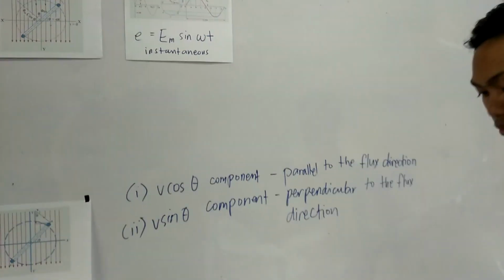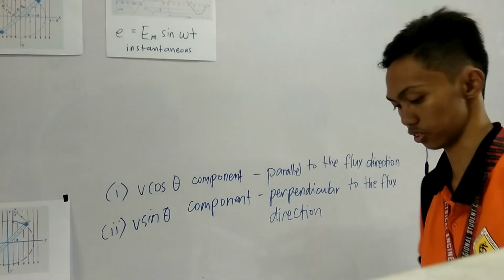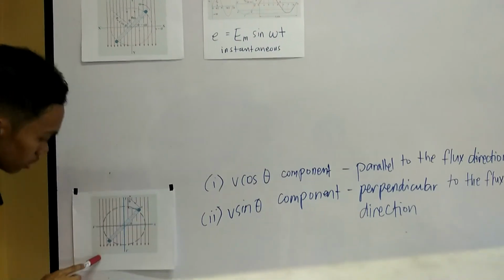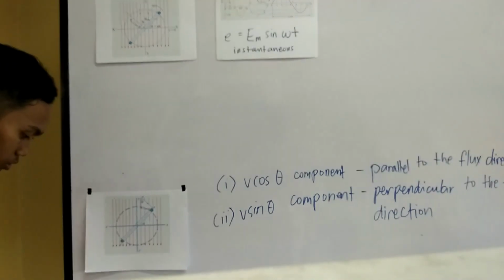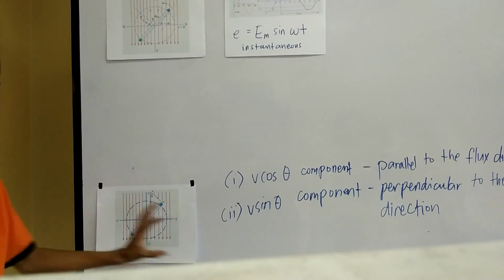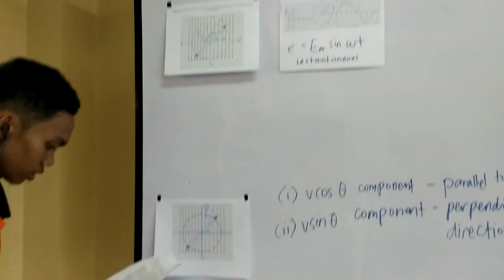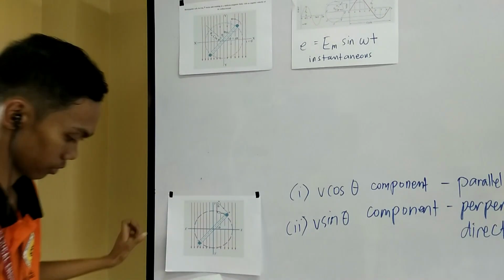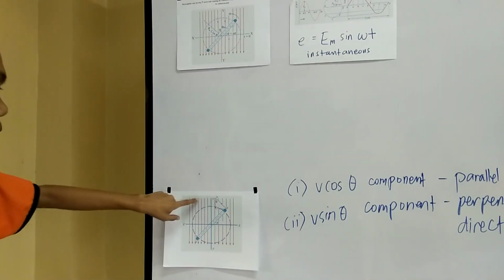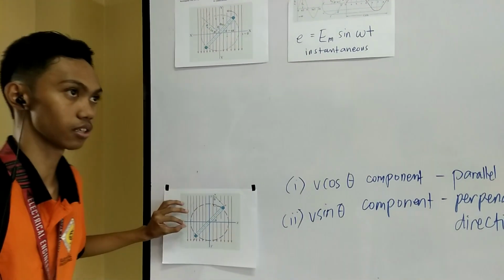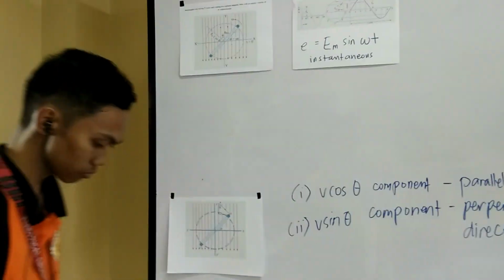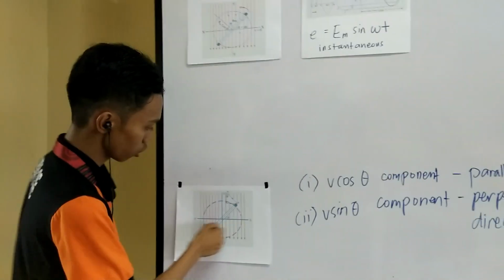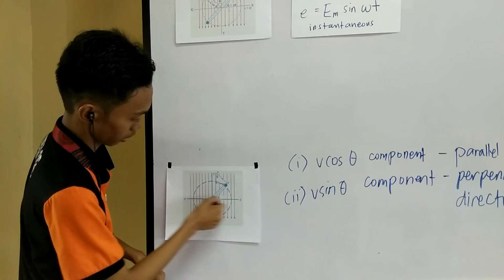Now let's talk about an alternate method for the equations of alternating voltages and currents. This figure shows a rectangular coil AC having N number of turns and rotated in a magnetic field of flux density B. Let the length of each side of AC be L meters and their peripheral velocity be v meters per second. So rotation is now expressed in meters per second. Let the angle be measured from the horizontal position also, so the reference for angle measurement is the x-axis.